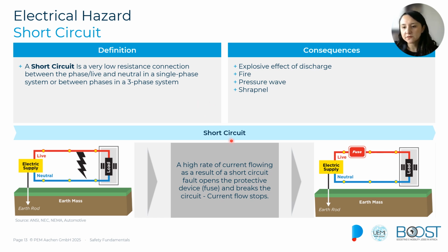In the specific case of short circuits, very good friends of ours are the fuses and the circuit breakers that we can see over here. These are devices that can cut off the power automatically when there is a fault and a high amount of current flowing through the circuit. This prevents overheating and will prevent more damage from the short circuit. And finally, another recommendation is to keep the workspace very clean, to keep the work areas free from tools, to avoid any accidental short circuits.